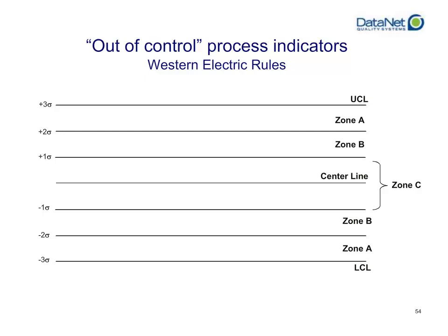So going from left to right, the different out-of-control process indicators that you might see according to the Western Electric rules are the 1 point beyond zone A, meaning even a single subgroup of data that falls outside of zone A is a cause for investigation, and an assignable cause is possibly in play. The next out-of-control indicator in this set is the 2 out of 3 points in zone A or beyond.